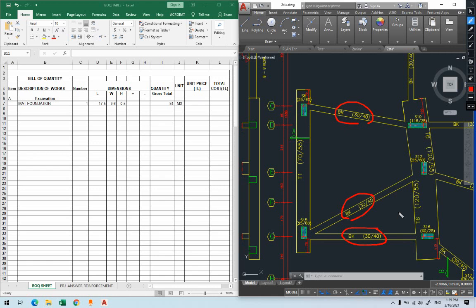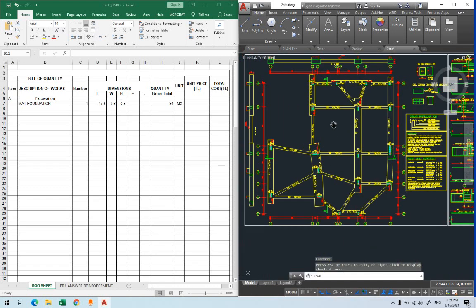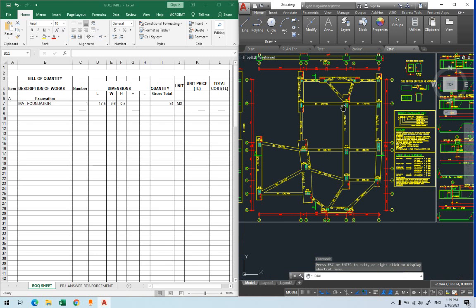Now what is the idea of ground beams here? If you have a single footing or a combined footing, normally you have ground beams that connect the columns to each other to make it a stable foundation, so that all of them work together. This is in the foundation design. You will learn this detailing. If you realize here, everything is linked together. So you have the footings.